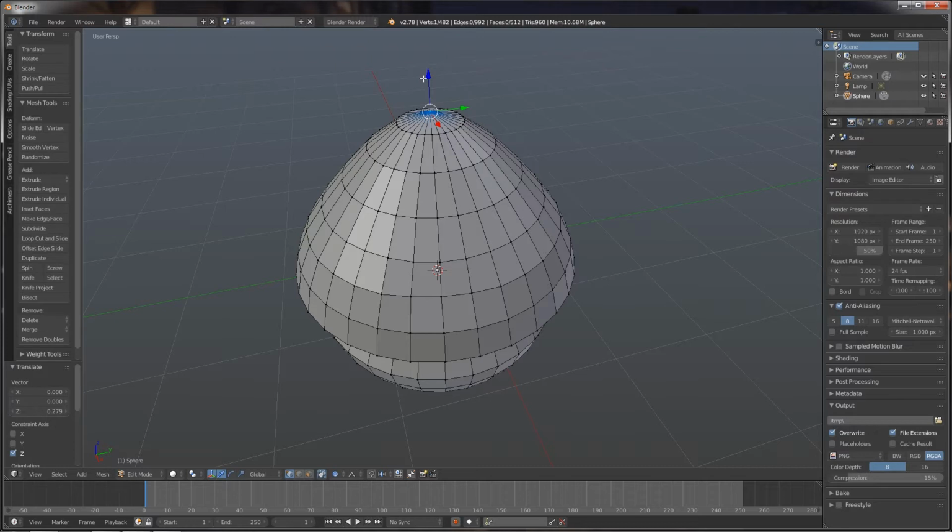We can also change the amount of area that we are affecting. Choose the topmost vertex and then the G key. You will notice a circle surrounding the cursor. Scrolling up and down with the middle mouse button or using the page up and page down keys on the keyboard will allow us to change the amount of area that we affect.